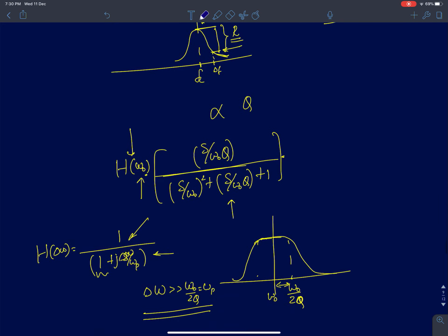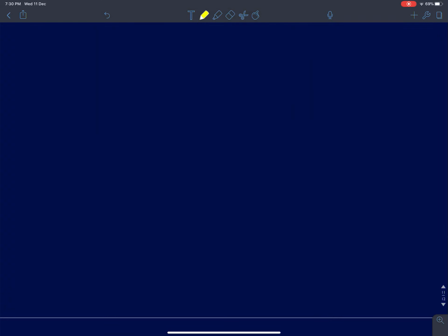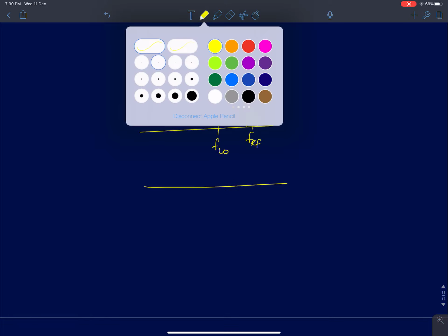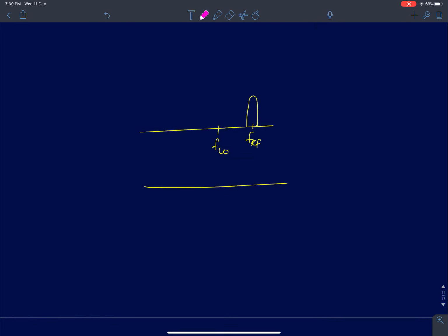But heterodyne receivers come with a host of its own problems. One of the main problems which I discussed in the class is the image frequency. So if you have, this is your local oscillator frequency, I said your RF frequency, say, is here, FRF is the RF frequency, then the image frequency will be here. I mean the intermediate frequency will be somewhere here. This will be FLO minus FRF. That will be your intermediate frequency.